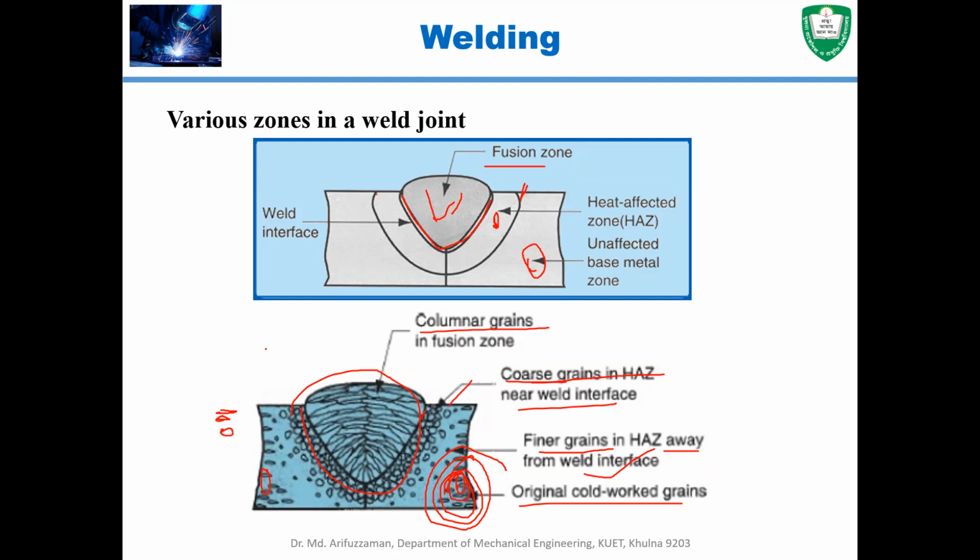Sir, in the face of the weld, we can see that there is some extra material from the base, but is it necessary in the final product? Actually, it is not necessary. In most cases, that reinforcement in this location is actually ground off if you need a plain surface, and if you don't need a plain surface, you can just leave it like that.